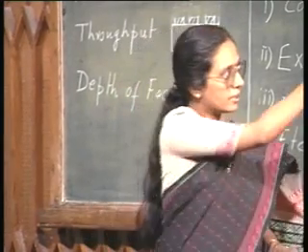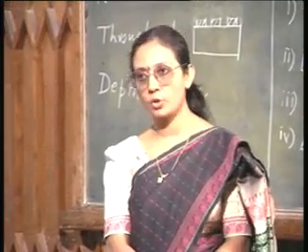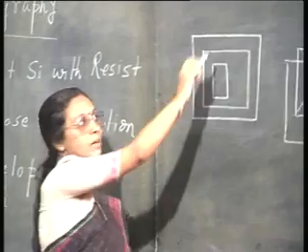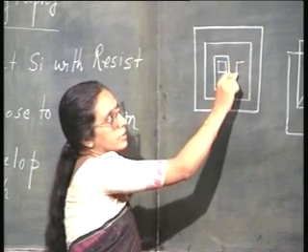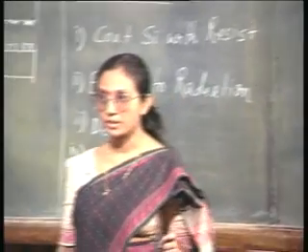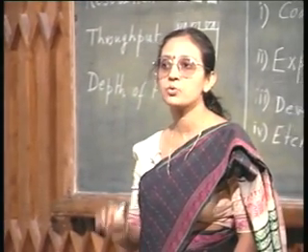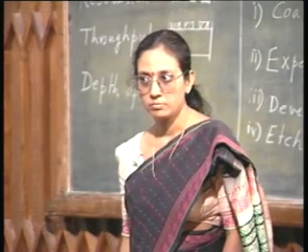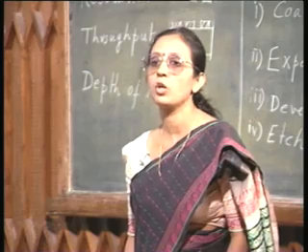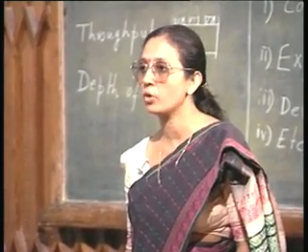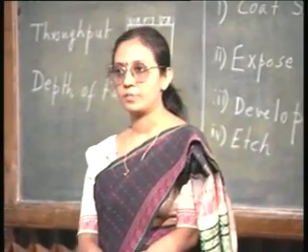First of all, like I started to do for this bipolar junction transistor, you complete the composite mask drawing. That is, you see, I have defined the active area, I have defined the junction isolation, I have the base diffusion. Now, I must have the emitter and the collector pocket and then the contact metallization, etc. So, this is my first step. I prepare a composite set of masks, how they should be with respect to each other. That is where the junction isolation should fall with respect to the active area, where the base diffusion should fall with respect to the active area, where the emitter diffusion should fall with respect to the base diffusion, and like that. Then this is your first step in mask making.